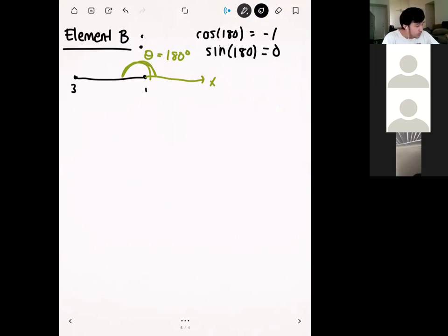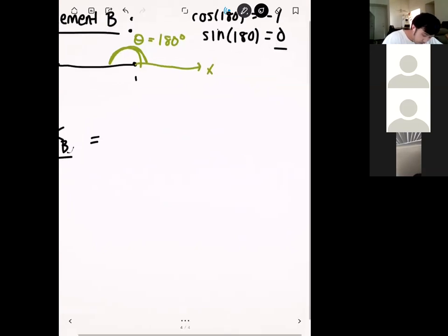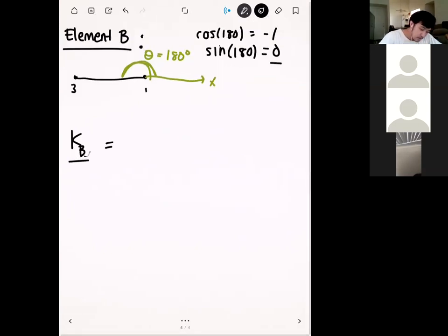All right, so then once we fill these into the element stiffness matrix, it's going to look like this, right? It's nice when our elements are either 0, 180, 90, 270. So because we have the 0 right here, a lot of things are going to cancel out. Right? So this is going to be, let me make this a little bit more clear. Right, so this is going to be 5E5.